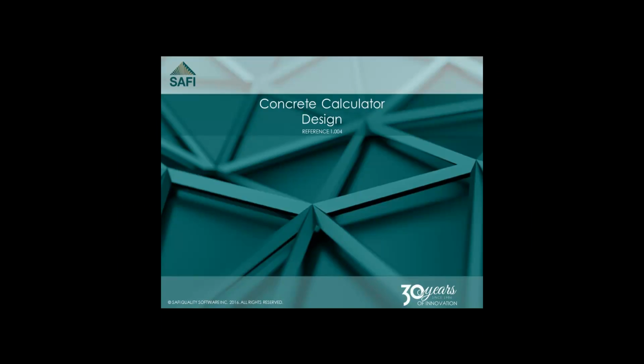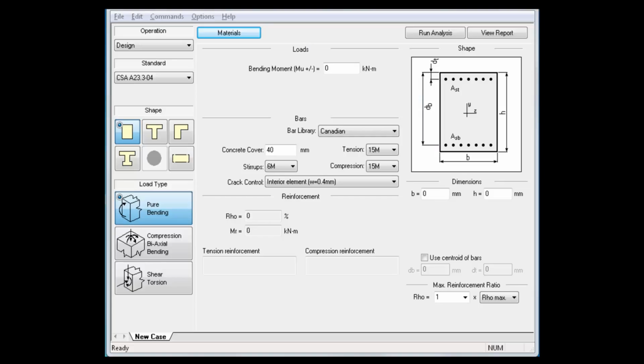For the design of a beam section in pure bending, 4 inputs are needed: the bending moment applied on the section, the dimensions of the sections, the reinforcement ratio, and the type of steel reinforcement bars used for the design. The bending moment can be indicated in the text box in the upper part of the calculator.